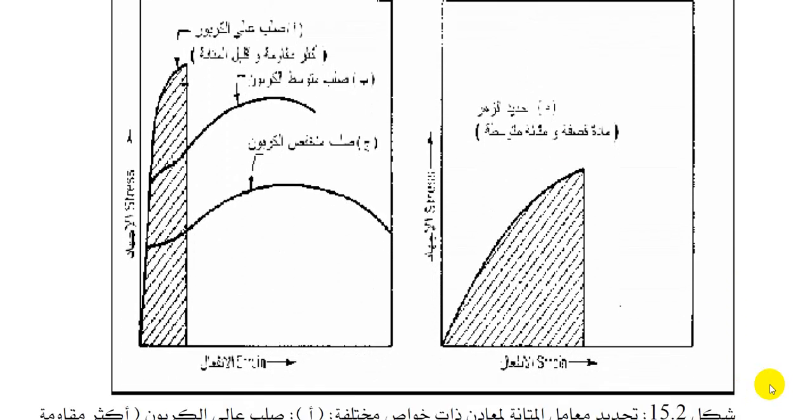The following two subsequent figures, as you can see right in front of you, indicate the high carbon steel and the cast iron toughness, the shaded toughness area bounded for the cast iron, as well as the high carbon steel toughness area bounded. As you can see, the dashed, or shaded, area, just like we stipulated before, is the toughness as compared to the corresponding strength. This is the higher strength and moderate toughness.